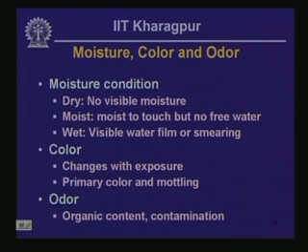You also have to include the description of the secondary coloration, such as patches of a secondary color. These patches are often called mottling, and this feature is associated with groundwater, with seasonal or time dependent groundwater fluctuation within layers.